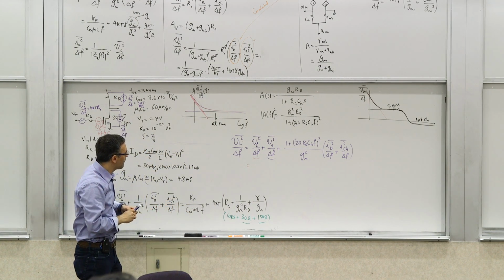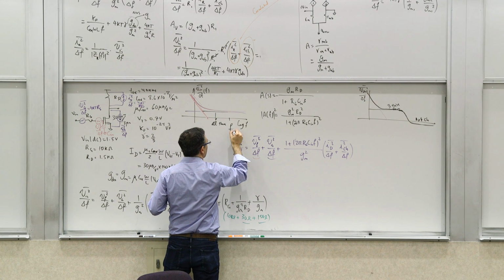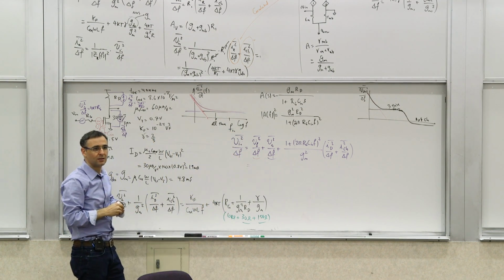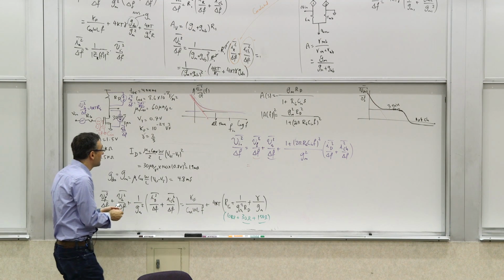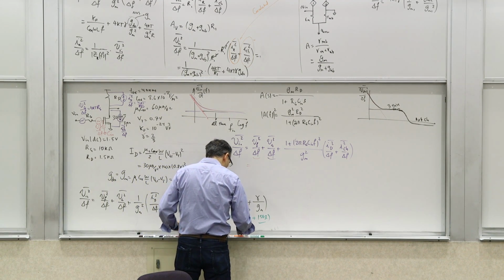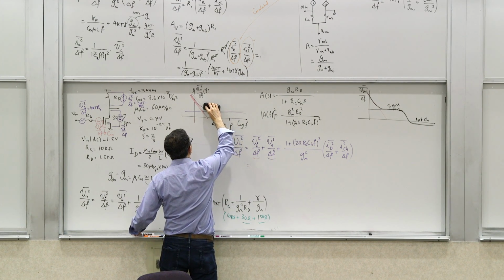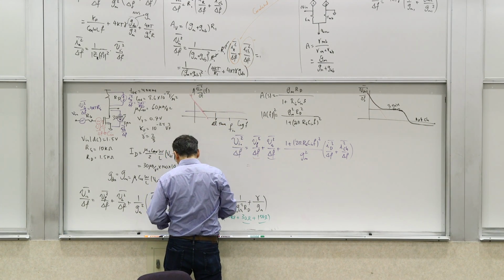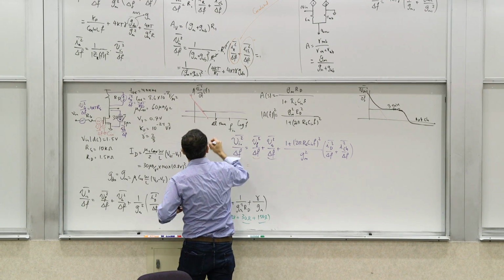But now, when you hit that frequency, let's say, I don't know, F in, what would happen to the input referred noise? It increases. So the input referred noise of this circuit will look like this, because now you have an increase, and it's a square dependence on frequency.